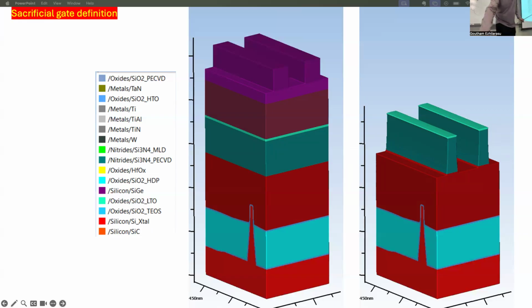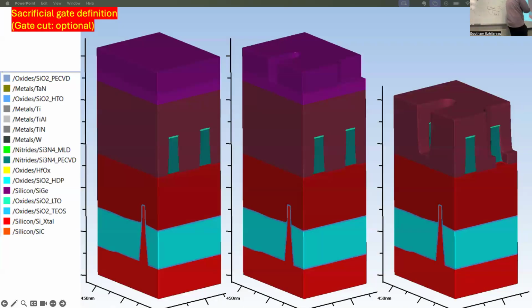So here is an example of a cut mask for the gates. Again, you do a 3-step resist process. So there's a planarization layer, SiARC, resist, and this is the cut mask for cutting the gates, right? So you pattern this, and then you basically transfer the pattern to the ODL, and then you etch this nitride. So now you have cut the gate at certain regions, right?